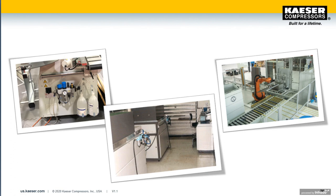Some uses are not so straightforward. Just looking at those three applications here, it will not tell you the full story. Observing them in operation might give you a hint. Measuring pressure and flow in short time intervals will actually tell you. Watch out again for these tiny hose lines feeding those applications or machines.